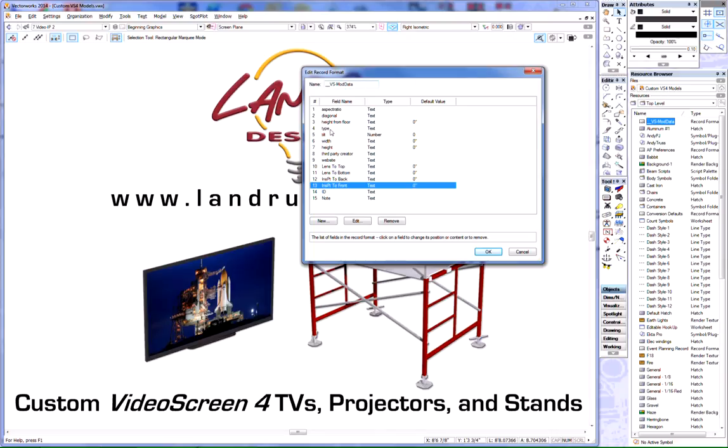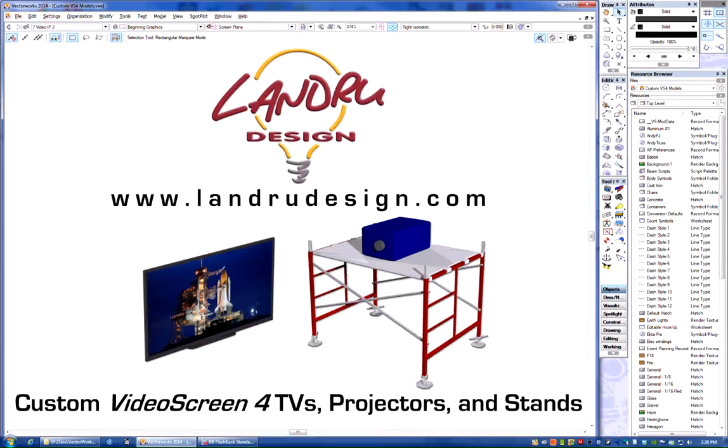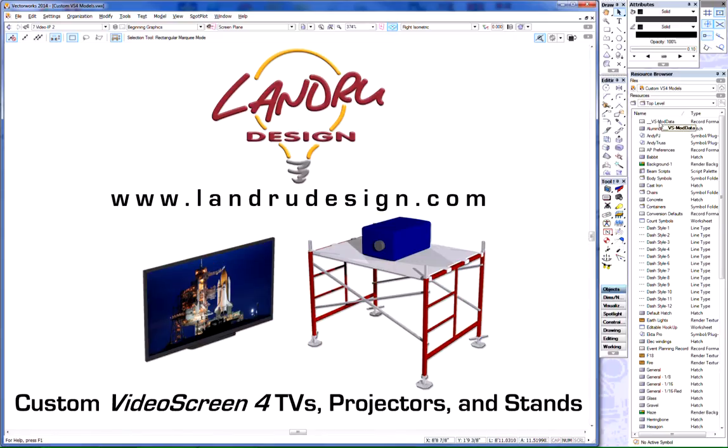The other thing I want you to see is this type field. Here it's blank, but this always will have to have either TV, projector, or stand included. If you don't see one of those three words, the symbol's not going to work and you're going to end up with errors. So again, we've got symbols, they're stored in resource folders, and they've all got this record applied. So let's take a look at the individual symbols.